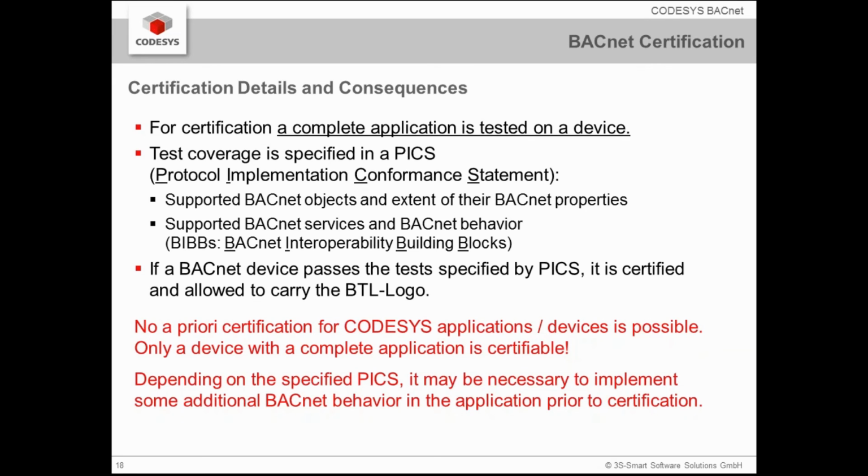Simply, if a BACnet device passes those tests specified by the PICS, it is certified and allowed to carry the BTL logo. A very important piece of information is that no a priori certification for CODESYS applications or CODESYS devices is possible, so only a device with a complete application is certifiable. And depending on the specified PICS, it may be necessary to implement some additional BACnet behavior in the application prior to certification.